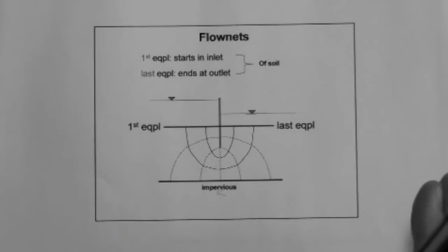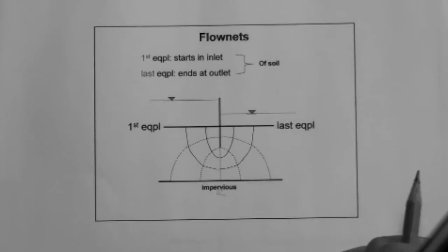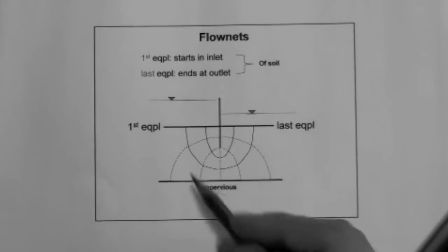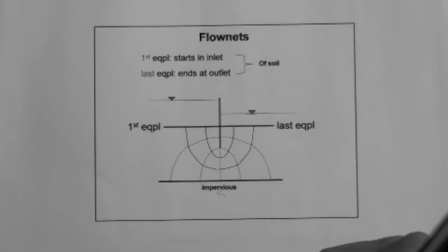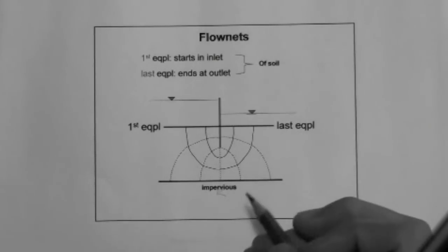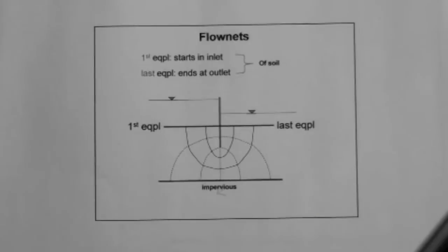it is very important once you have your flow net, and ideally you would want to be able to draw the flow net. It's very important as geotech engineers to have some experience in actually drawing a flow net, and you'll see later, in the next slide, we're going to talk about how to draw it. But essentially, what we do now in the field is we use computers to draw the flow nets for us because they are more precise than us.